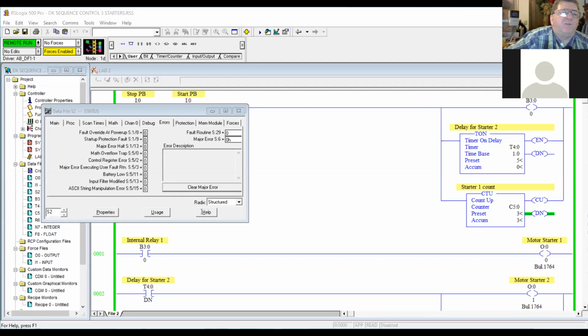So if something's wrong with the base hardware on the PLC, you might have a fault code B. If it's a fault code 12, your ladder program has a memory integrity problem. There may be something wrong with your program. Fault code 15, your user I/O configuration is invalid. In other words, you may not be telling the program the right modules that you've plugged in or added onto the PLC, for instance.